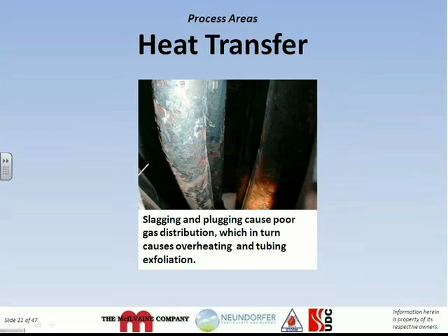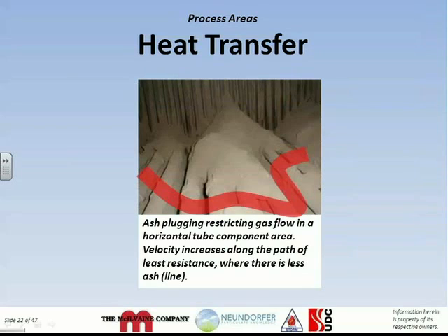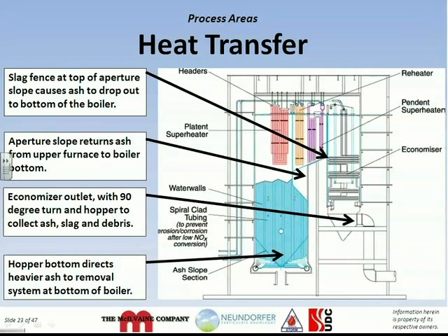Coal fuel ash corrosion, for example, is temperature dependent for the corrosive chemical species to form. Plugging causes more unpredictability in the location of this corrosion and makes managing the condition far more complex and therefore more expensive to control. The erosion thinning rate of the tube increases with the square of the velocity of the combustion gases. Slagging causes high velocity in some zones and low velocity in others. Therefore, high thinning in some locales and less thinning in others. When the boiler is not fouled due to slag and ash, it breathes more easily and more predictably.